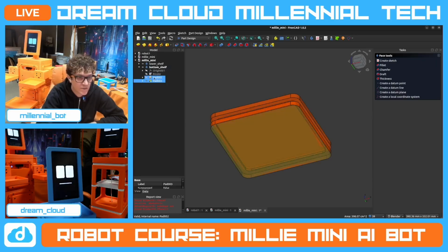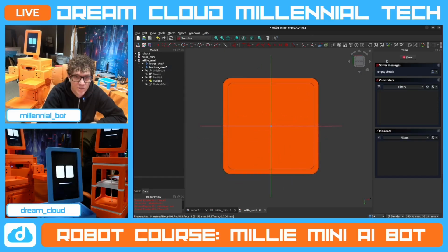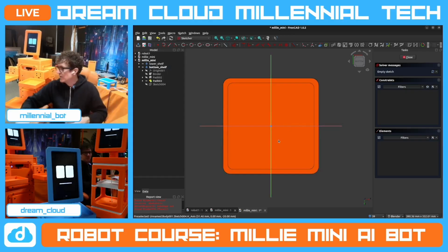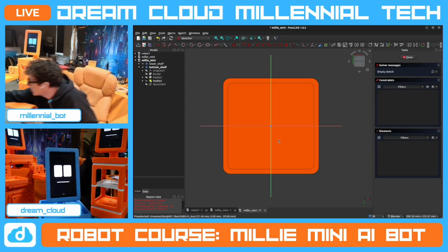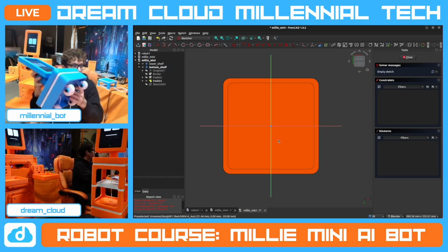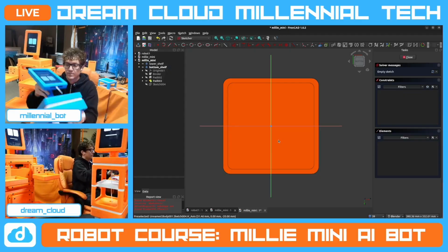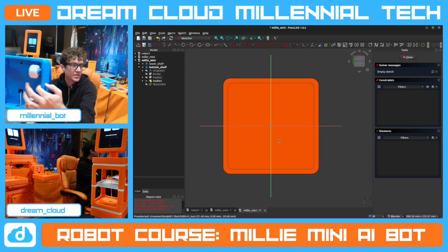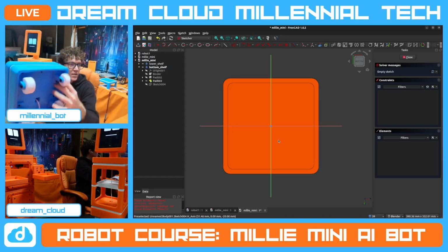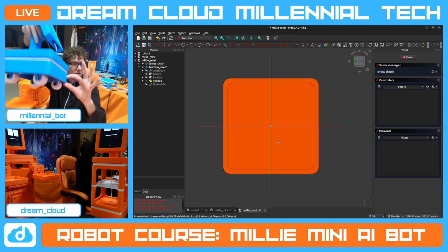So again, we do the same thing. We create a sketch. We make sure that this is bold, that we're in the bottom shelf, and we make sure that we select that face, which brings up the face tools, and then we create a sketch. Now, what is this sketch? This sketch, my friends, and I guess I could show you on, no, I'll show you on this. This sketch is going to be this extruded part. So if you look right here, this lip right here is extruded, right? This whole kind of vertical dimension right here, we need to create that.